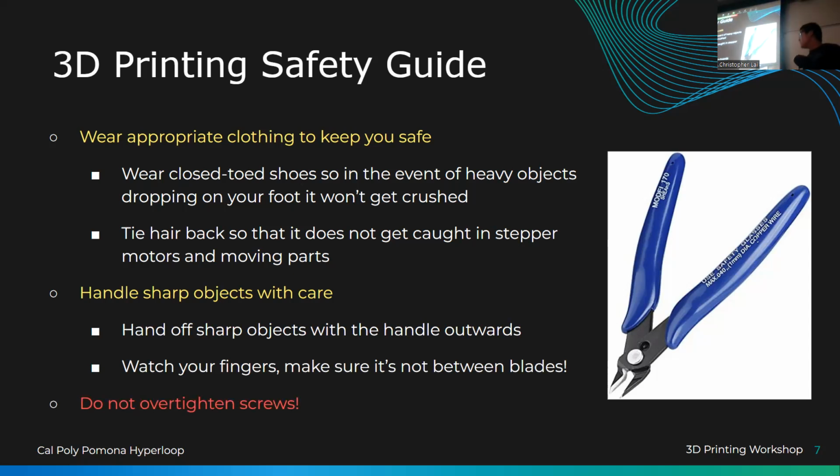Okay, the most important point, I think: when we did this last semester, we actually built 3D printers. This semester, we're just going to have templates for you. But in general, if you want to build your own 3D printer in the future, it's really important not to over-tighten screws. When you're tightening screws and there are 4 or 5 screws in a pattern, you're going to loosely tighten them all first and then go in a star pattern. Basically, you tighten one screw a little bit, then go to the other corner and tighten it a little bit, and then the next corner.